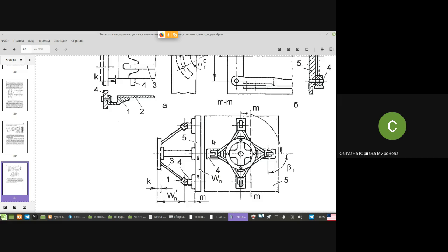And it means that in the jig, each time you have a special locator, which is responsible for positioning the part with this GPH hole. And I hope you do remember that it comes to holes not just joined by bolts. It comes to holes which are empty. Empty during some stages of assembling. Empty until they meet each other in different aggregates, maybe even at final assembling already, not even section assembling, but final assembling.